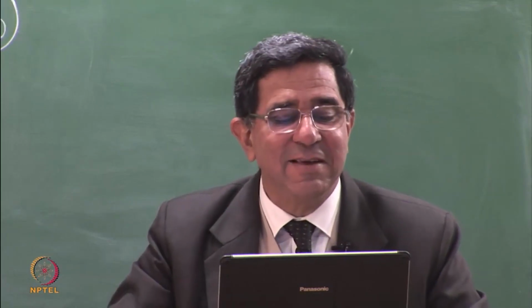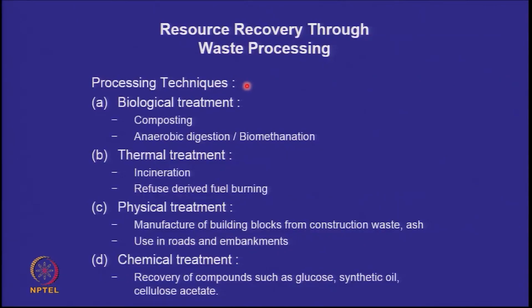Right? So anyways, after recycling and reuse, you can do processing. You can convert your municipal solid waste into compost by aerobic processes and anaerobic digestion. You can do biomethanization. Methane can give you energy. You can do thermal treatment. You can burn it. From the municipal solid waste, you can take out the paper and the plastic and the rags for refuse-derived fuel, which can be used for energy recovery.